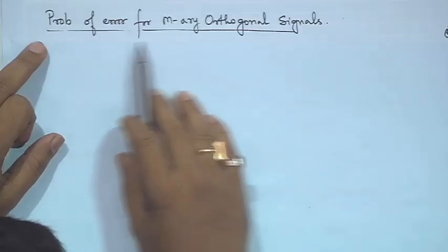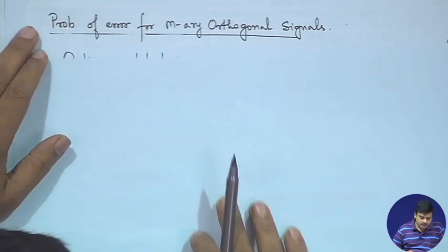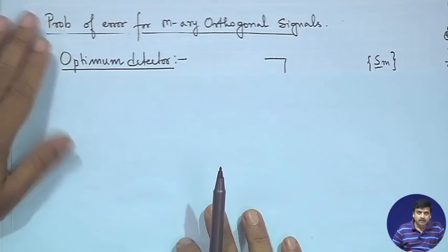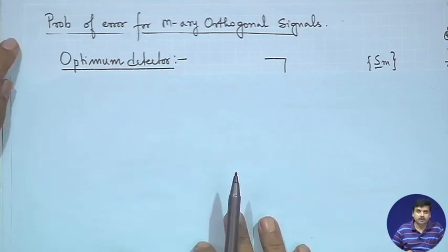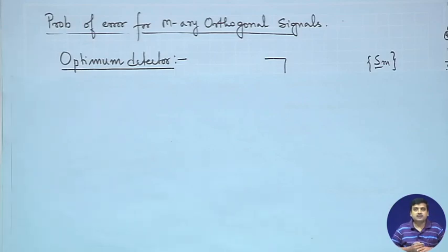So, in the study of the M-ary orthogonal signals, we will take a look at the optimum detector. We have discussed what is meant by the optimum detector and how it is realized. There are several realizations. Just to remind, we started off with the posterior probabilities, which we expanded using Bayes rule, where the denominator term did not influence the decision, and in the numerator term there was the multiplication of the likelihood function by the prior probabilities.